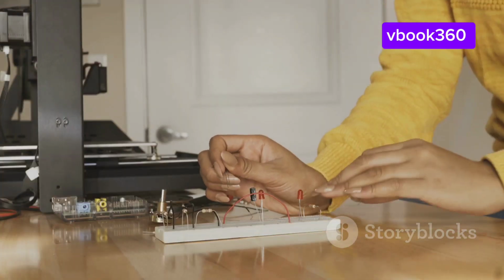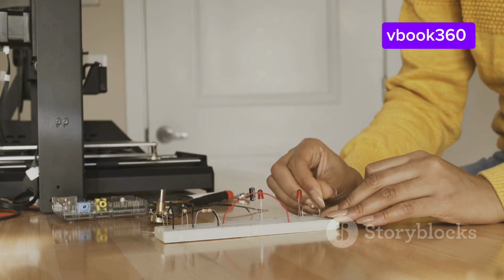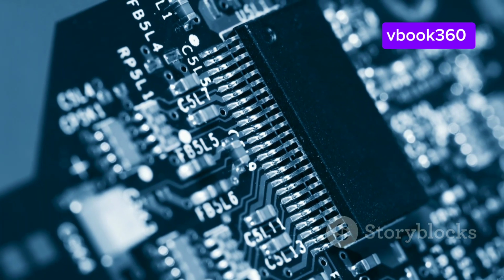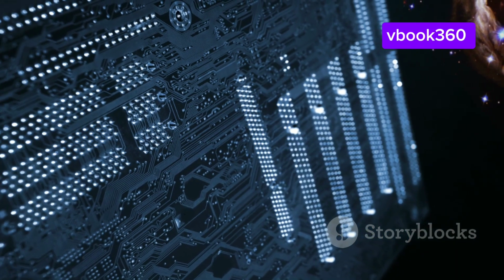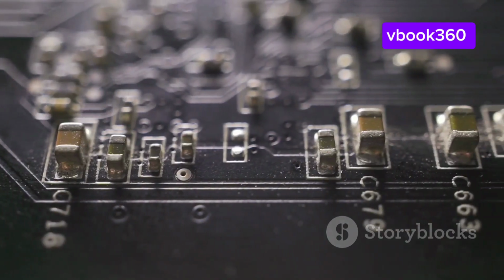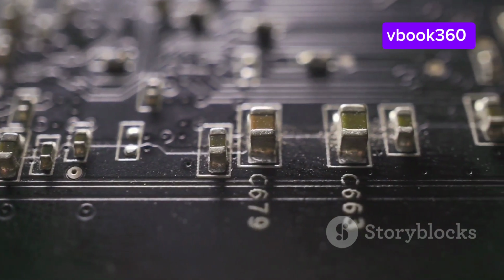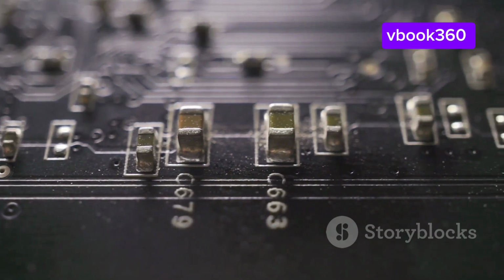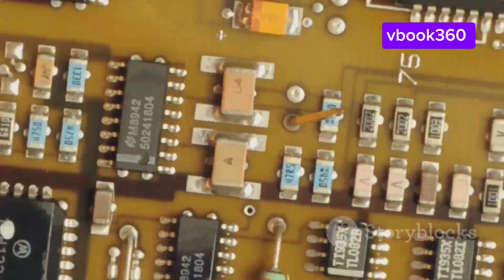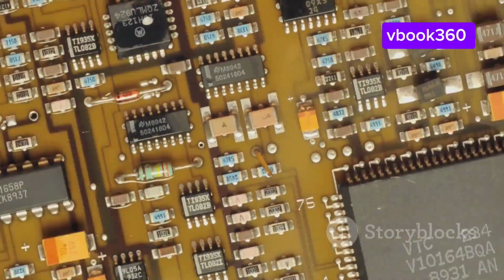Voltage dividers. Resistors can be configured as voltage dividers to create a lower voltage from a higher voltage source. This technique is commonly used in sensor circuits to scale down the sensor's output voltage to a level suitable for an analog-to-digital converter, ADC. Timing circuits. Resistors, in conjunction with capacitors, form the foundation of timing circuits, which are used to generate delays, control the frequency of oscillators, and create time-based events. By adjusting the resistance and capacitance values, you can fine-tune the timing characteristics of the circuit.